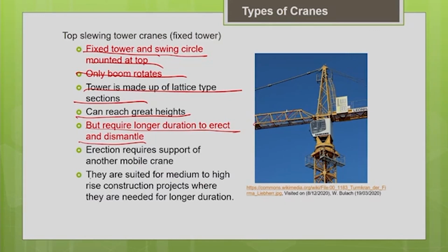So they are generally suited for medium to high rise construction projects where they are needed for a longer duration. For a longer duration, this can be justified. The erection cost, dismantling cost and mobilization cost can be justified if you need this crane for a longer duration at a project site.